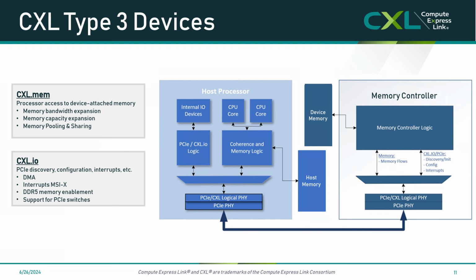To start, I wanted to take a step back and talk through CXL as a high-speed, high-capacity interconnect for CPU to device or memory connections. As it is built on top of the PCIe physical and electrical interface, it includes a PCIe-based block input-output protocol, CXL.io, used typically for discovery, configuration, and interrupts, as well as new cache-coherent protocols for accessing system memory: CXL.cache and device memory, CXL.mem.